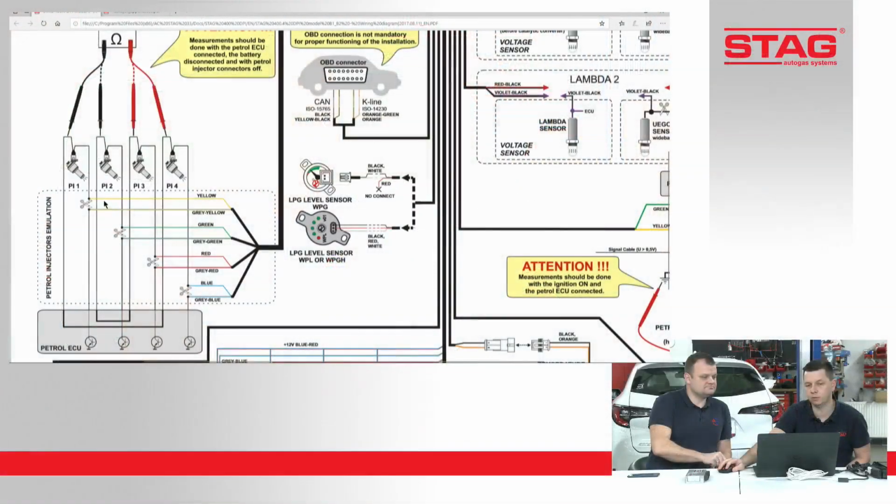So this is a factor that you cannot easily handle, and see the end effect. Just after a while of driving, you will notice that the gas dosage is very low and the corrections go minus. It means it's too rich, because both fuels are flowing in parallel in the cylinder. Right. And the second thing is if you make the wrong connection.